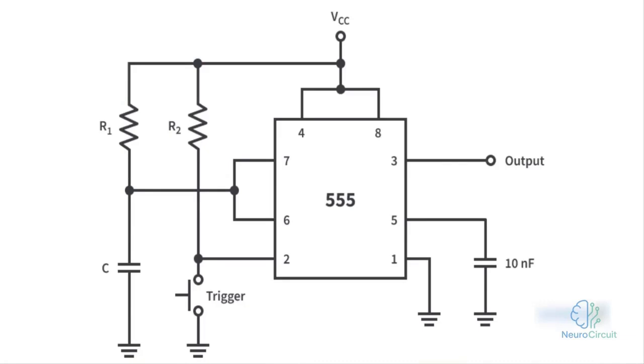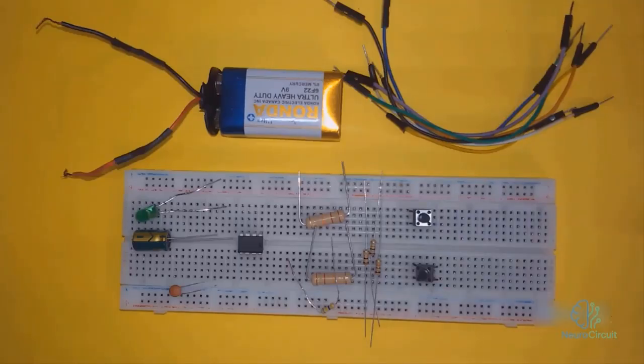So for this situation, you can use several types of resistors. For example, you could use a 10 kilo-ohm resistor, and for your capacitor, you could use a 100 microfarad capacitor, which could be a ceramic one. Or it could be another resistor with a different value. That really depends on you and whatever resistor you have on hand. And if, for example, you only have a 10 kilo-ohm or a 1000 ohm resistor, it doesn't matter. You can use it for this purpose, and let's change these values together and see how the amount of time it takes for the capacitor to charge changes.